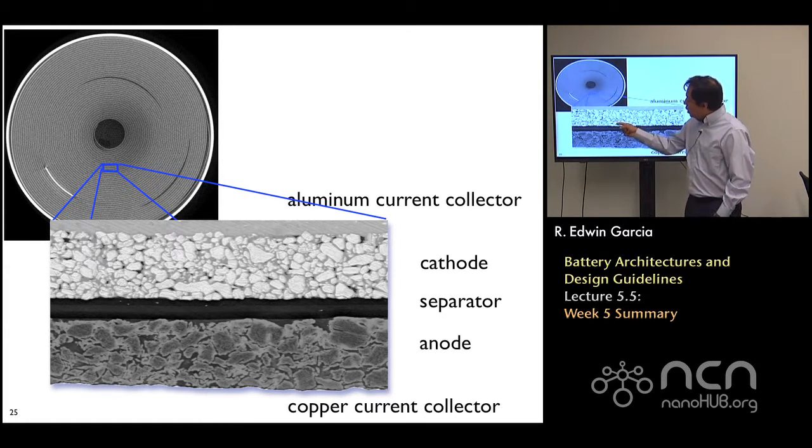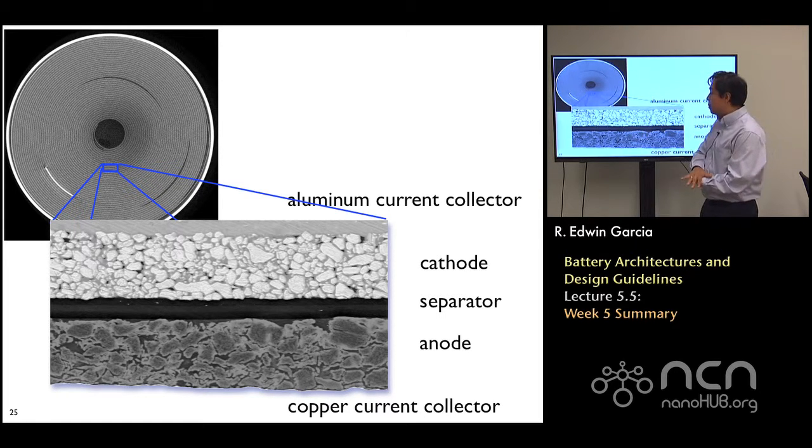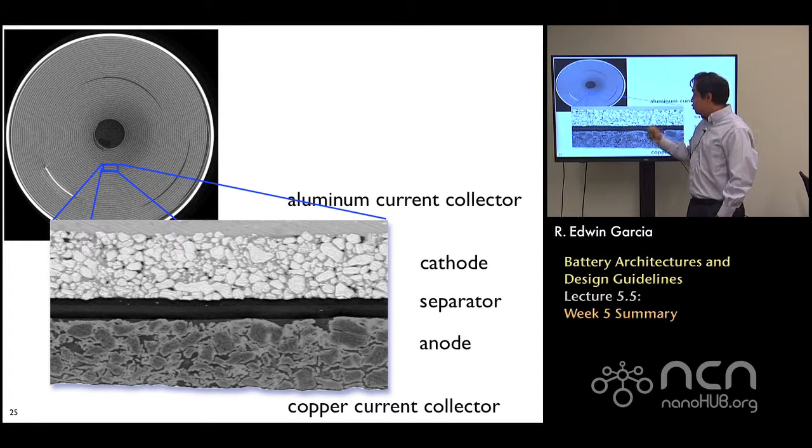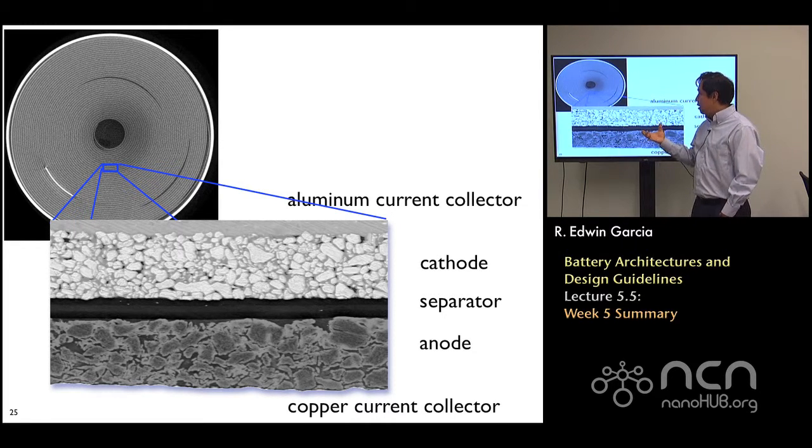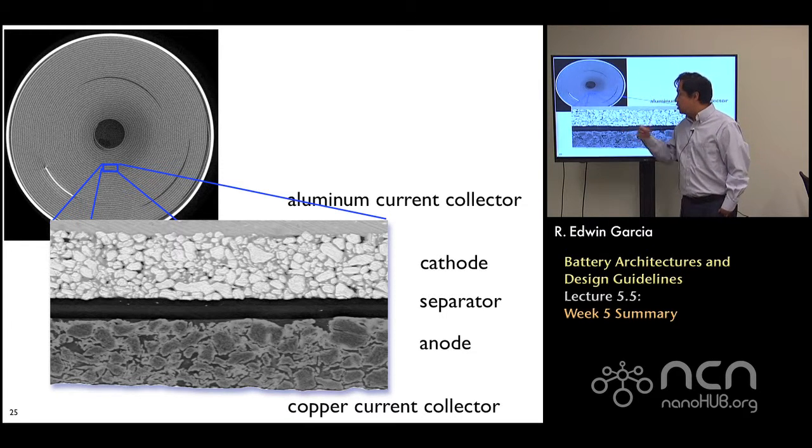Not only why these particles are aligned. We discussed how compaction becomes an important process in increasing the energy density. You can see how the particles are effectively non-spherical, yet we think about them in those terms to rationalize them better, and how we have particle size inhomogeneities that are unavoidable as a result of processing, but lead to specific losses in the cell.